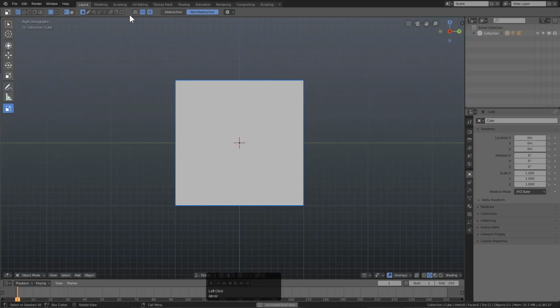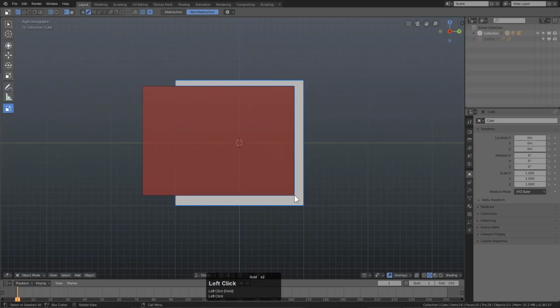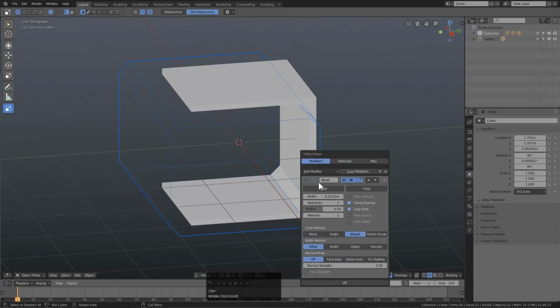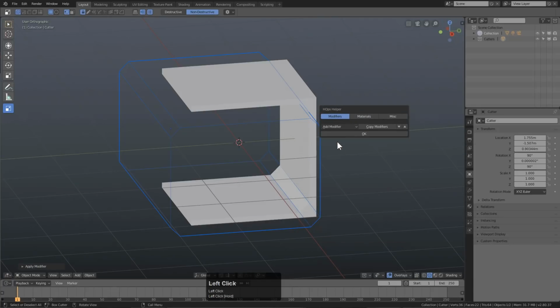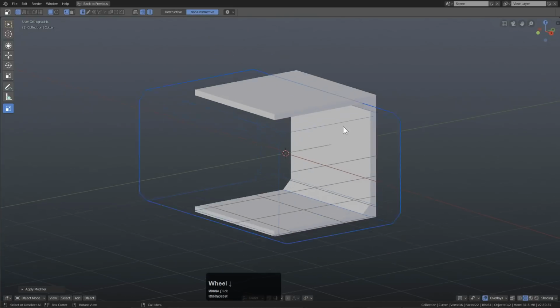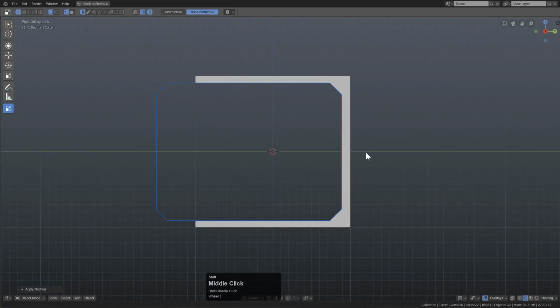We're starting off in box, and we're just going to draw a red box using left mouse click. I'm going to press tab to drop that shape down, press B to bevel all the corners, individual corner beveling coming soon. From here I'm going to just hold shift in order to keep this shape live, and I'm going to press Control tilde to use the Hardops modifier helper to apply the modifiers. If you're not using Hardops, you can just go to the modifiers, but I like to pretend that thing's not even there, so I'll press shift space bar to really help myself get into the zone.